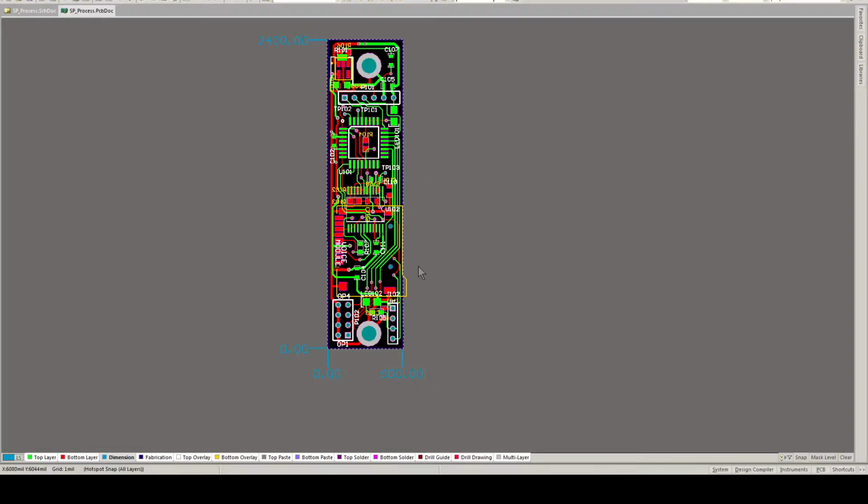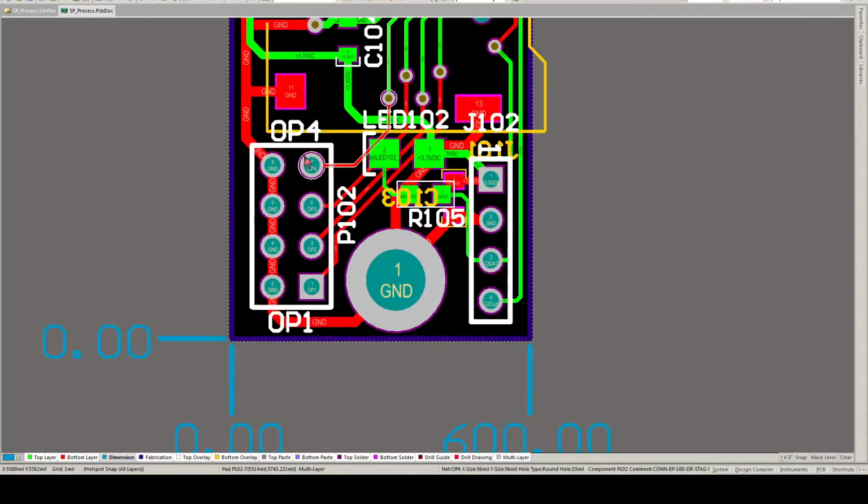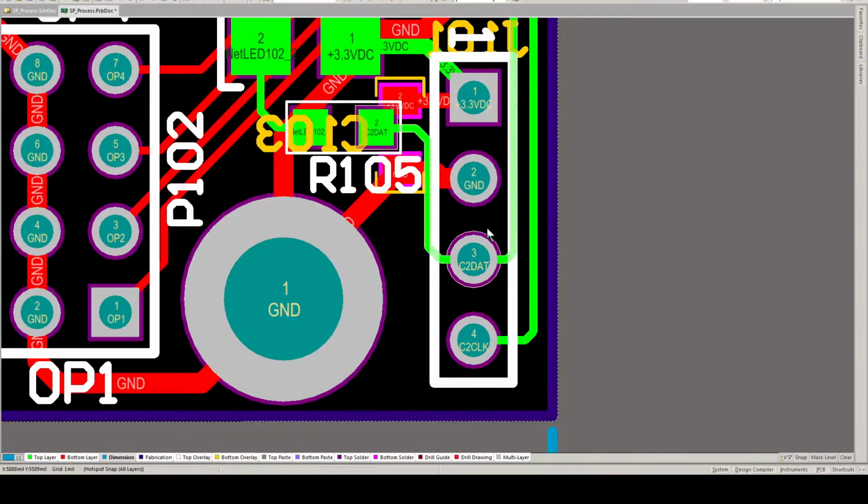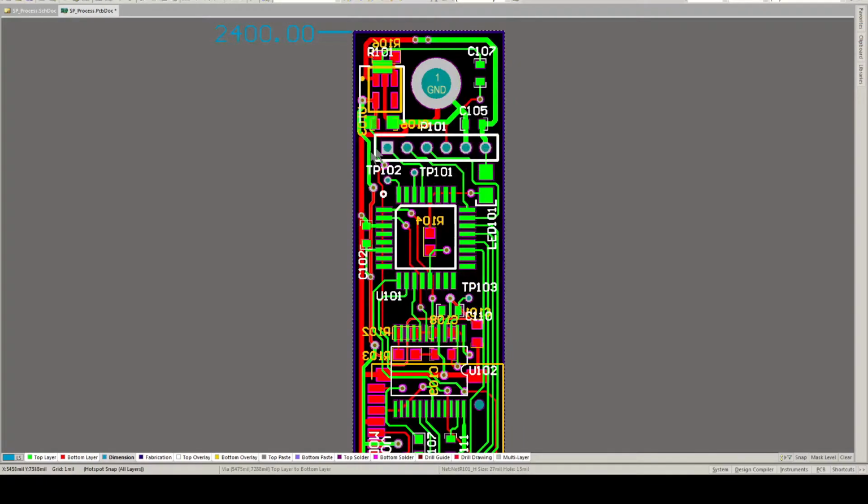On the bottom of the board is the SD, shown in yellow here, silkscreen at the bottom of the board. Here the SD card socket is right here. Microcontroller, speech processor IC. Down here we have option pins, which I haven't assigned to anything yet. They're just spare pins for now that can be assigned in software. And programming header right here for programming the micro. And the I/O port, which goes down to the main board. So we're ready to generate Gerber files and order boards.